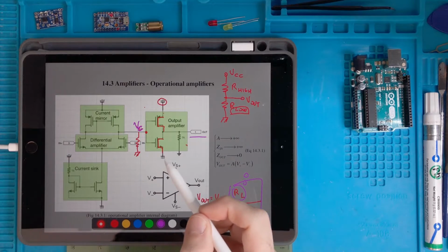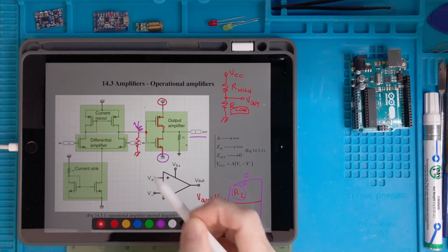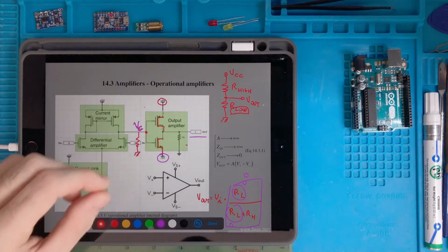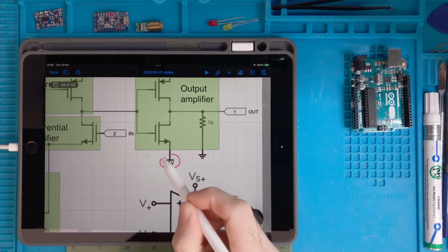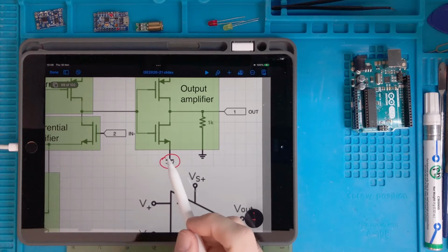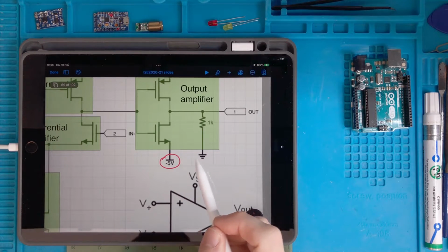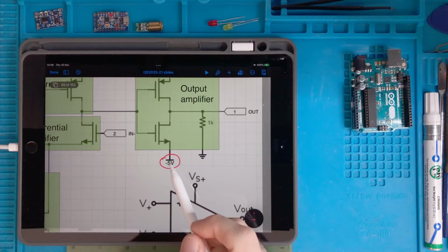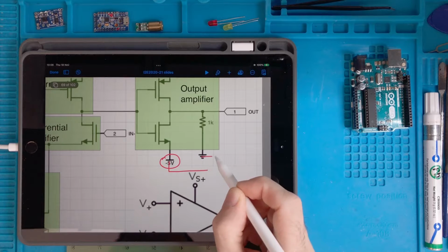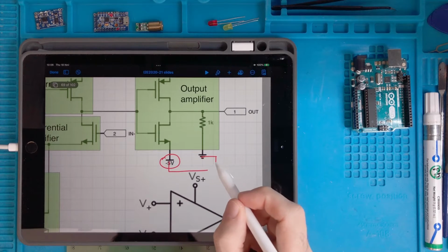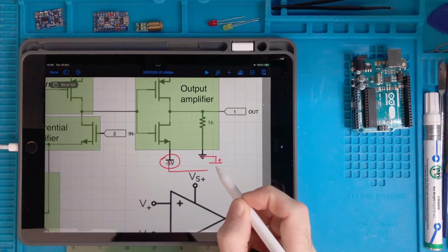Now it's not 0, but it's -5, because we applied a secondary voltage source here. So we bias this transistor not with the ground, but with a negative voltage respect to it, which means that from this node to this one there is a battery connected with this polarity.